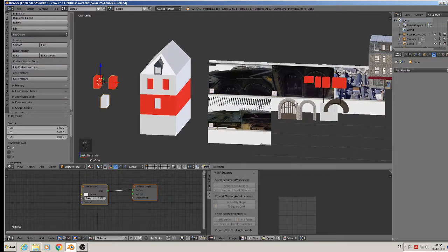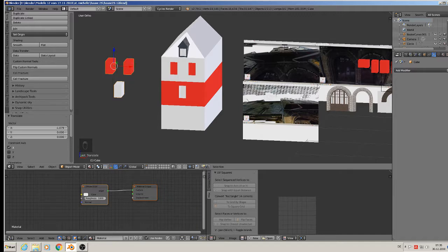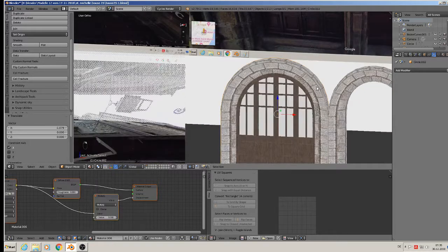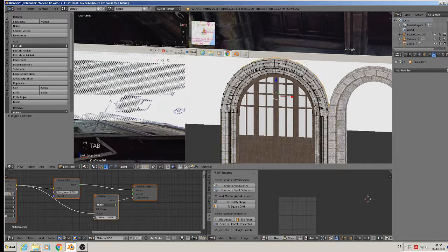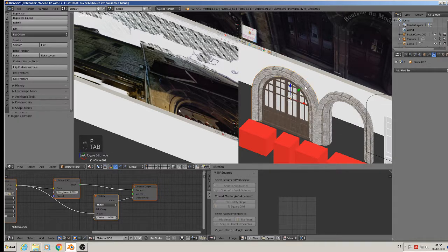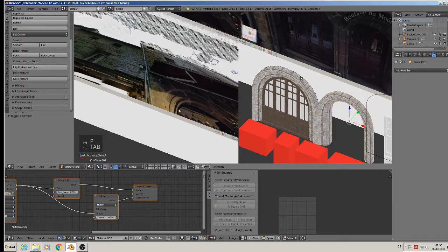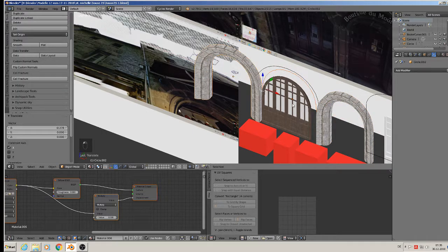So now the round bows must be cut down there. And it is important that we can't scale them too much because then later that doesn't fit there. So here we take the back face, Shift D, P to separate the selection. Same we do with that one. Shift D, P to separate selection. Now we have two singular bows.